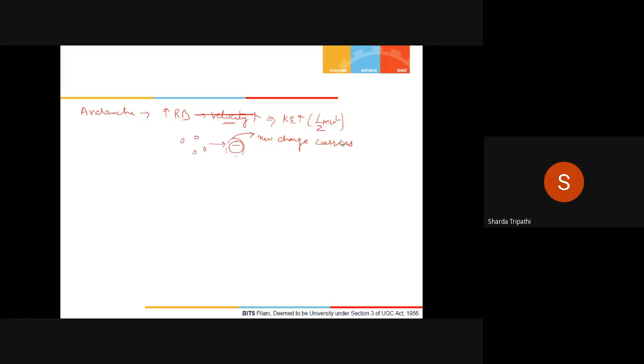But now, because of the collision, what will happen is that the energy of these minority charge carriers which are coming through the depletion region gets absorbed by the electrons in the outermost shell of that particular ion, thereby dislodging these particular electrons, and in turn you have more charge carriers being created, electrons as well as holes also.